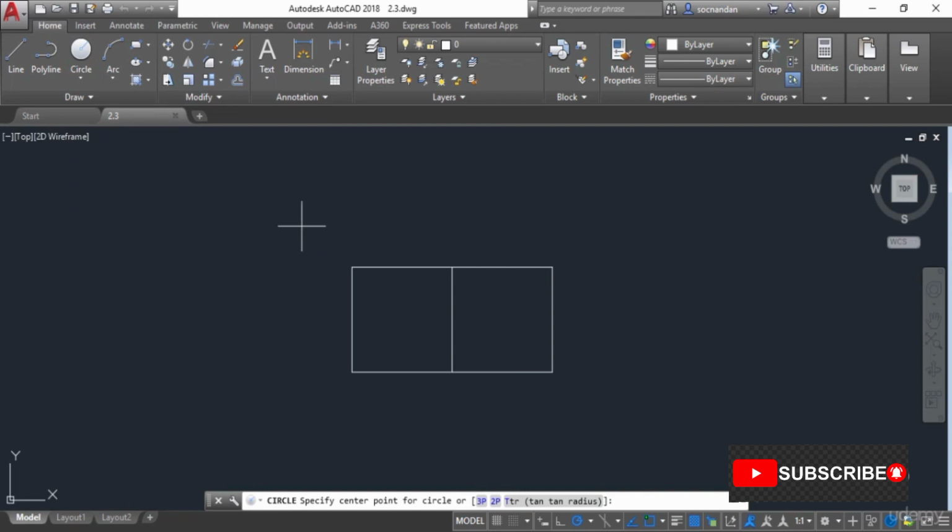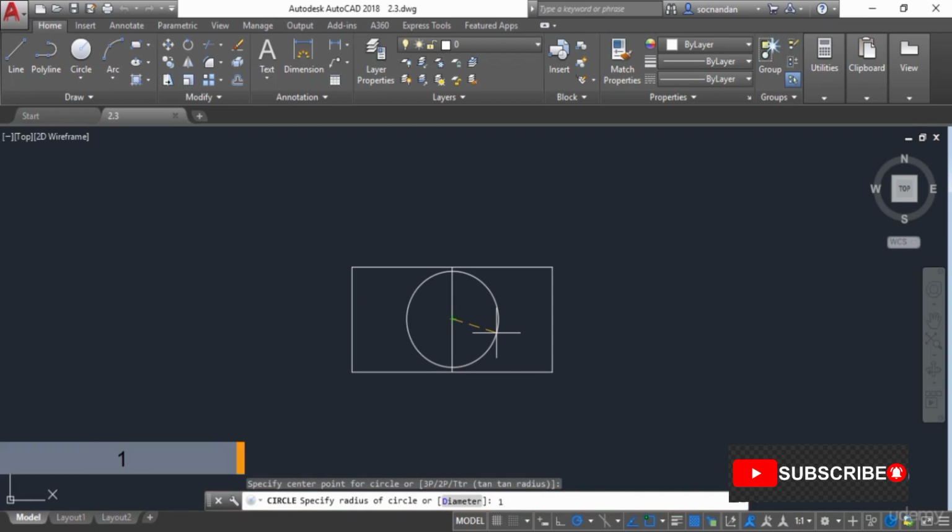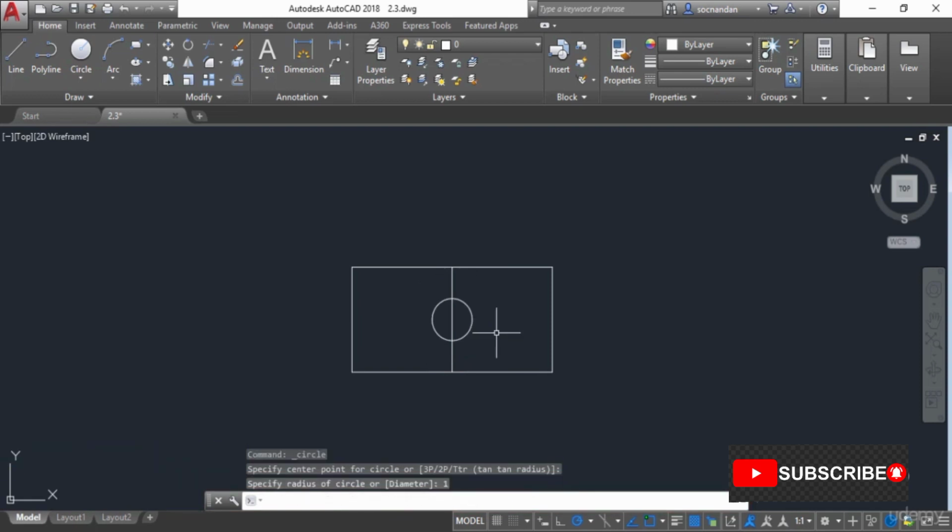Now after starting the command, click at the point from where you want to start the circle, and in this case we want to start the circle from this midpoint of this rectangular geometry. So I'll click at this point, and this will be the center of our circle. Now look at the command line, and it prompts you to specify the radius of this circle. So let's enter the radius of this circle as 1 unit and press enter. So now here we have it, the circle with a radius of 1 unit or a diameter of 2 units at the center of this line.